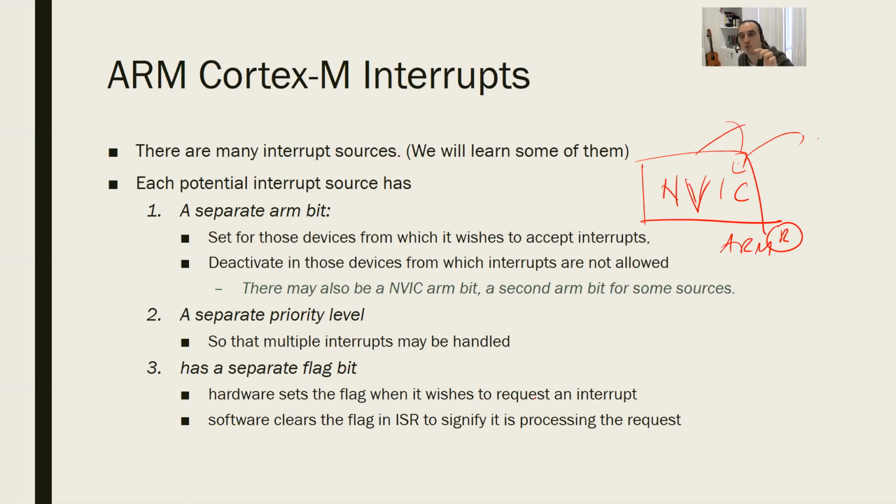And for the interrupt sources, we are going to cover the pins and the timer. We are going to talk about this. The timer will need only a single step of enabling. The pins will require 2 steps of arming the bits. So the first step for any interrupts, you will change 1 or 2 control register bits to arm that bit for an interrupt. Any questions?